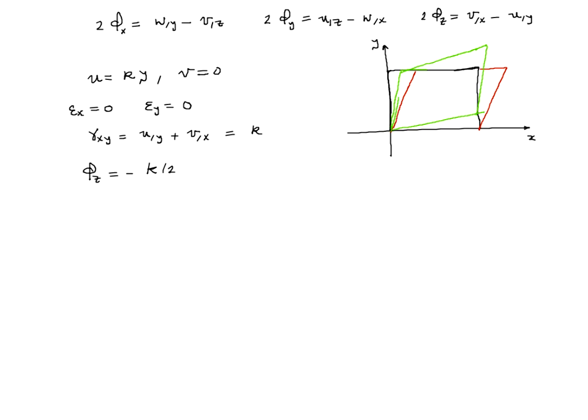So let us think about it now this way: the displacement gradient H is composed of two parts: a symmetric part, which represents strain, and an anti-symmetric part, which can be written as either a 3x3 matrix, which we call phi, or, corresponding to that 3x3 matrix, as a 3x1 vector along the axis of rotation.